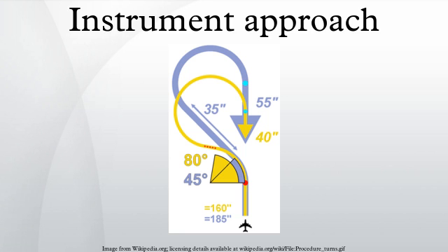A DH/DA denotes the altitude at which a missed approach procedure must be started. It does not preclude the aircraft from dipping below the prescribed DH/DA. A decision height is measured AGL, while a decision altitude is measured above MSL.